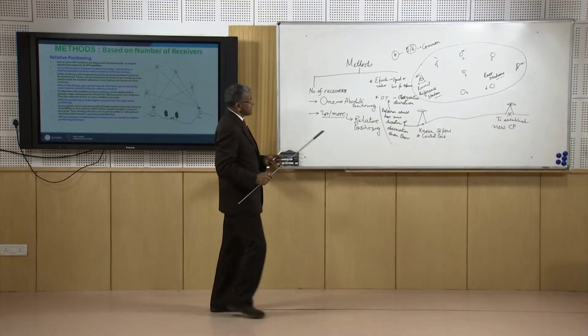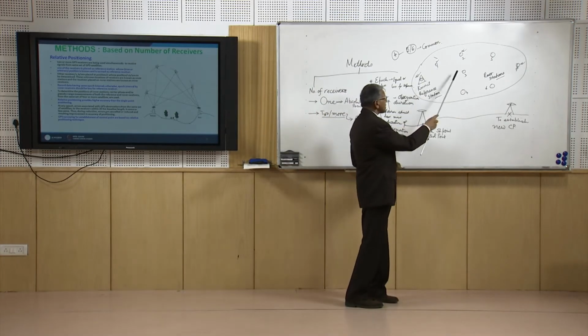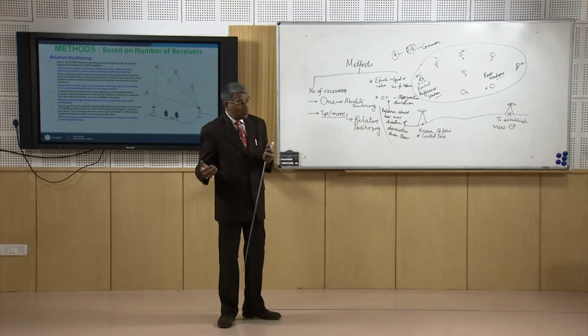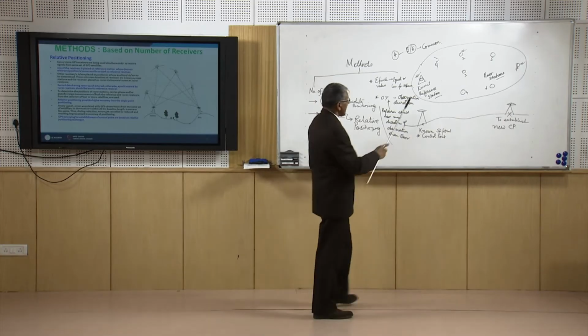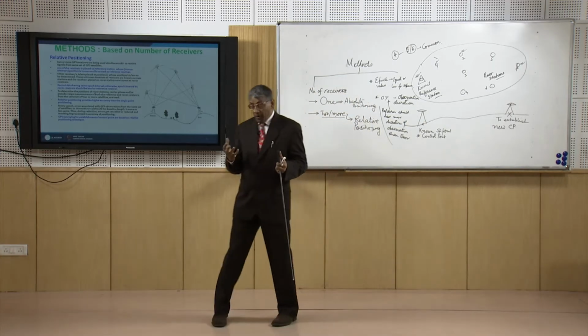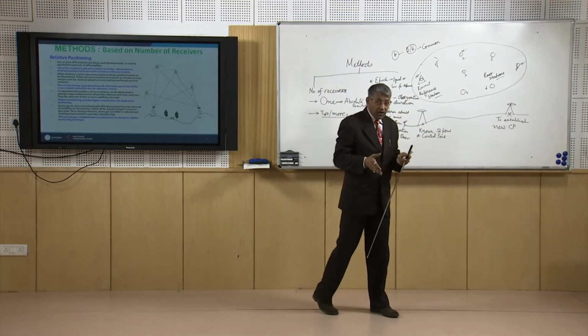It has been experimentally found that if the distance between the reference and rover is less than 20 kilometer, they are expected to receive signals coming through the same segment of ionosphere.